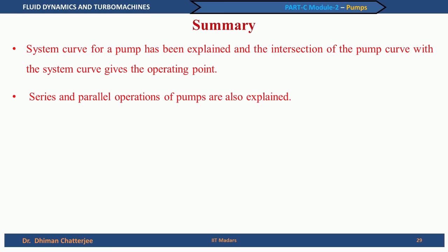So, this is important. Another point will come up, not today, in the lecture on cavitation: when we take a pump, it is not just the matching with the best efficiency point, we have to take into consideration that the pump does not cavitate, but that is a part of another discussion. We have also discussed how series and parallel operations of the pumps can be done. We will take up some problems in the tutorials this week, when we discuss how to solve the series and parallel operations of the pumps.